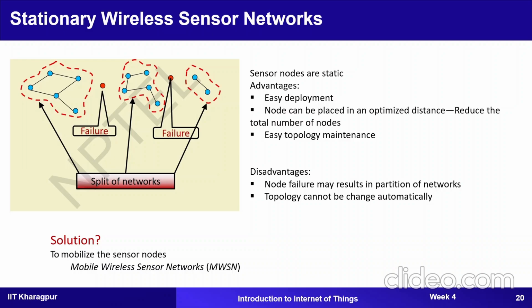And your high-end sensor nodes, so we don't need to deploy them very densely. They are able to handle the multimedia data also. So basically the high amount of large packet sizes they are able to handle with quality of service requirement. Mobility is there. The example of high-end sensor nodes are your smartphones, and these are generally applied to ITS and military or biomedical applications. So the correct option for this is your low-end sensor node. So low-end sensor nodes have no IP support.